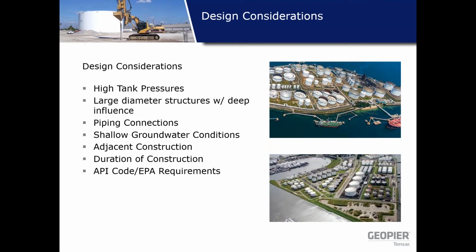Adjacent constructions. When you see two tanks in 2015, after 5 years the owner or the tank refinery probably wants to build five more tanks, and as the footprint or real estate with these tanks increases, you need to be careful considering the overlapping stresses on the foundation adjacent to the proposed tank locations.